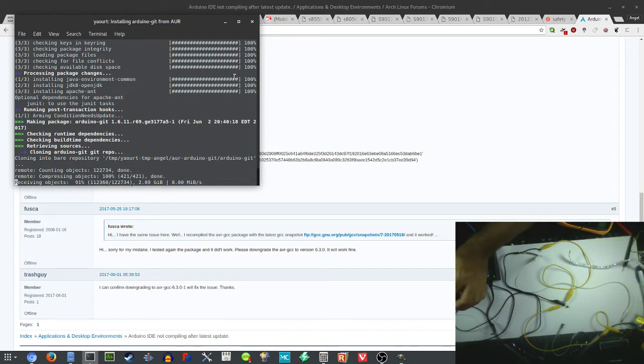Yeah, I think we're just gonna have to connect to the two grounds. So the ground from the power supply and the ground of the Arduino. So that means I'm gonna have to connect to the ground of the Arduino, and technically it's gonna be the same ground. If I connect it to the 3D printer, it's gonna be the same ground.